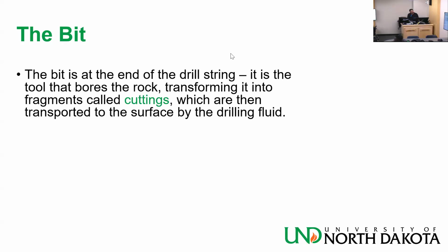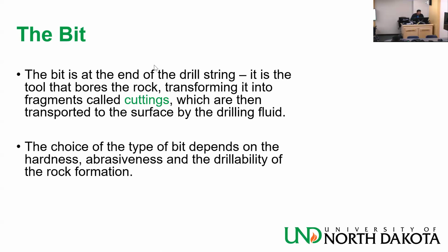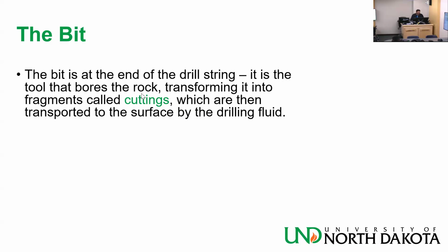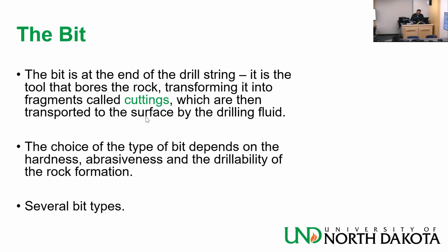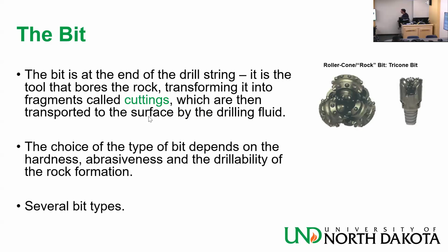So the bit is at the end of the drill string. It is a tool that bores the rock, transforming it into fragments called cuttings, which are then transported to the surface by the drilling fluid. The choice of bit type depends on the hardness, abrasiveness, and drillability of the rock formation. There are several bit types, but two main categories. The roller cone bit has rollers that move as you are rotating it.